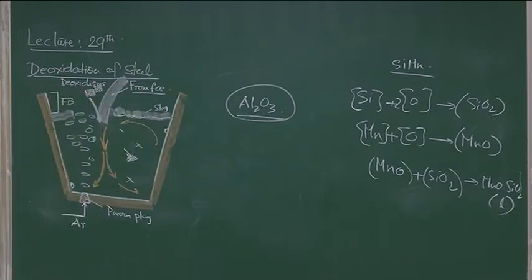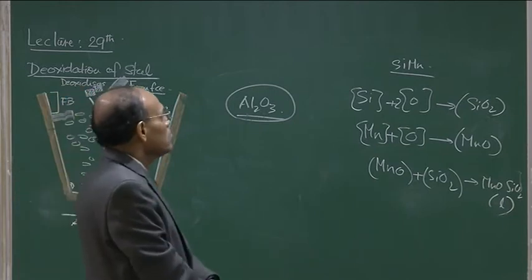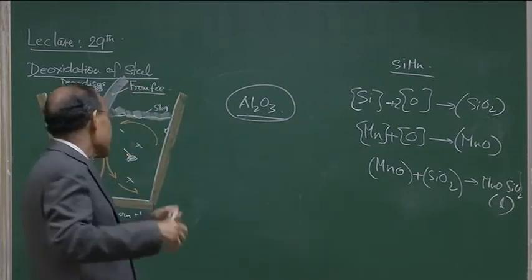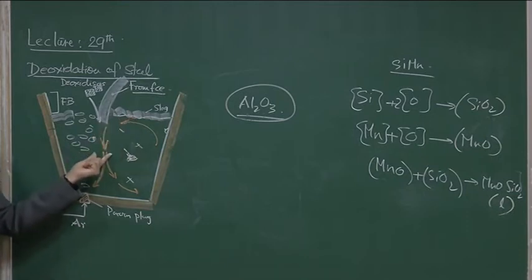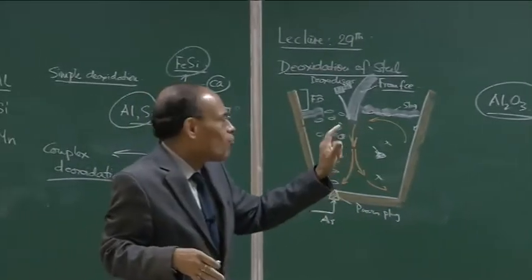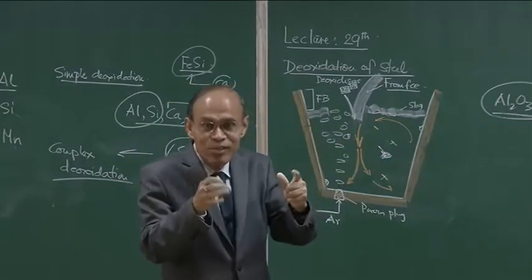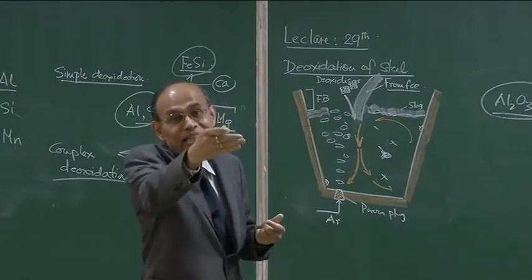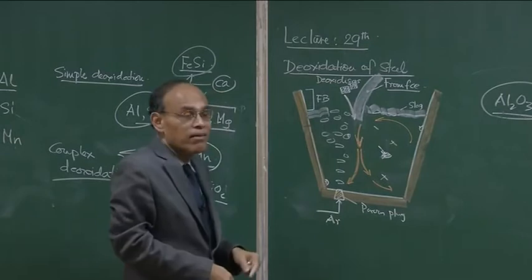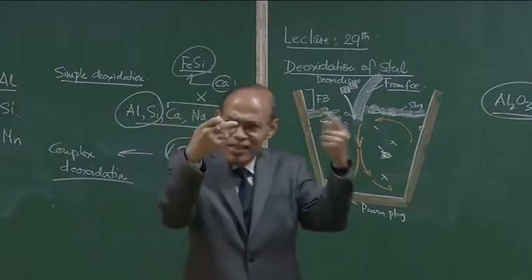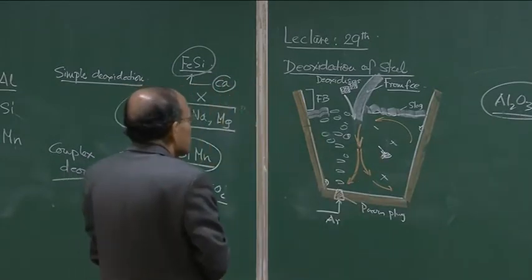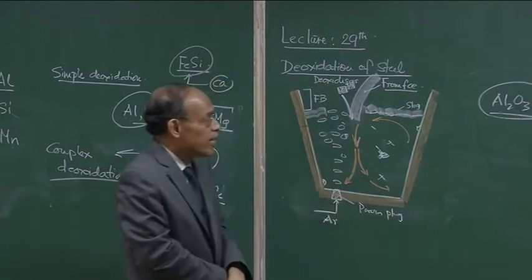So, if you want to do deoxidation by aluminum, you can determine a priori how much aluminum needs to be added in order to fulfill it, and of course, there could be, as I have indicated, 0.1% FeO, there could be some loss. So, you can add plus minus 5% or a little bit more. Whatever you are calculating is an ideal calculation, so there may be losses. So, you can back it up with an additional 5% and then add the deoxidizer element into steel, only ensure that there is a good amount of mixing, rapid melting and rapid dissolution, such that the reaction can really take place.